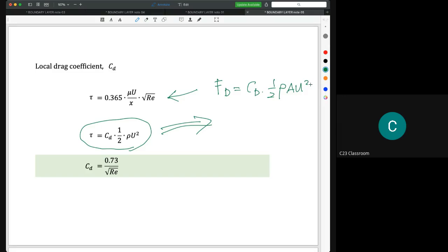So we found that the number is not matching, it's not the same. Why? Because there is resistance in real life, in the real experiment. So that's why in the calculation here we put a CD, meaning friction coefficient. Because this is calculated specifically for drag force, we call that coefficient a drag coefficient. Okay, that is the story. You know about the similarity, the Buckingham Pi theorem, and so on and so forth.